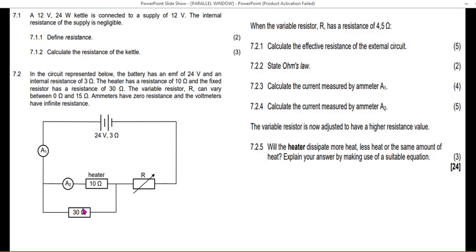They divide the total current inversely proportionally. That means the resistor with a higher resistance will take a low proportion of the current, and the one with a lower resistance will take a high proportion of the current.